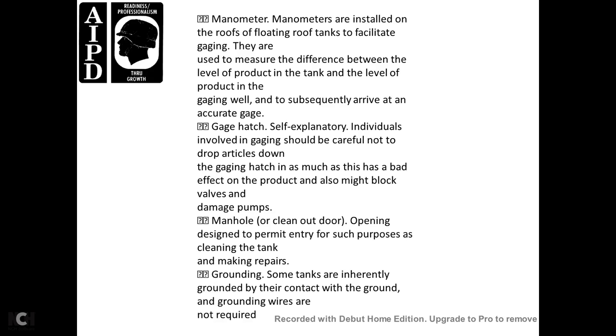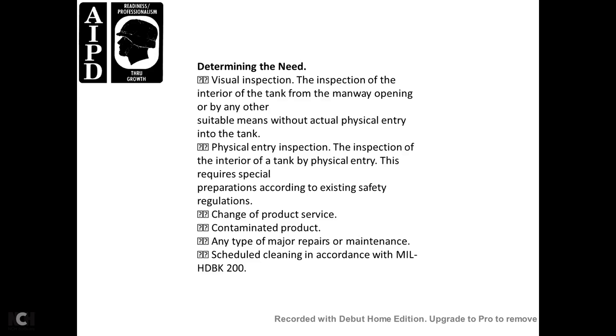Grounding. The steel tanks are inherently grounded. They conduct contact with the ground, and ground wires are not required. Determining needed inspection. Visual inspection. The inspection of the interior of the tank through the manway opening or any other suitable means, without actual physical entry into the tank.